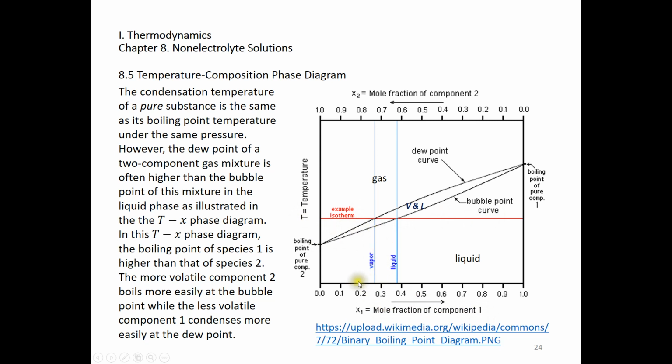So when you try to do this condensation to purify component 1, make sure you just drop to this dew point curve and collect just a little bit of the liquid phase. In that small amount of liquid phase, we have a mole fraction of 0.38 for component 1.